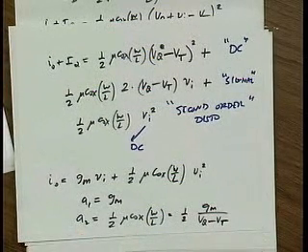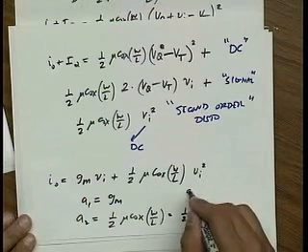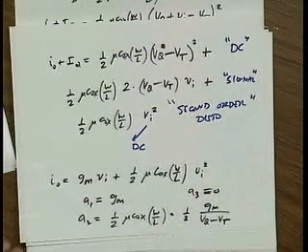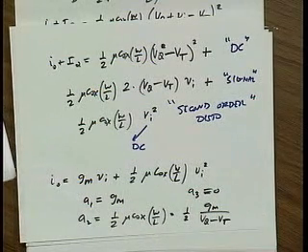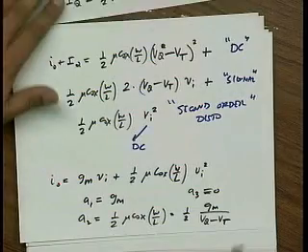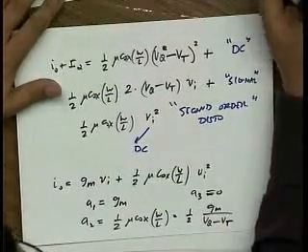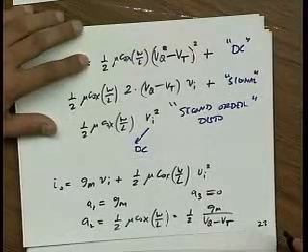And for a square law device, A3 is identically equal to 0. So if I actually have a square law device, I'm in business. I will generate no third order distortion.